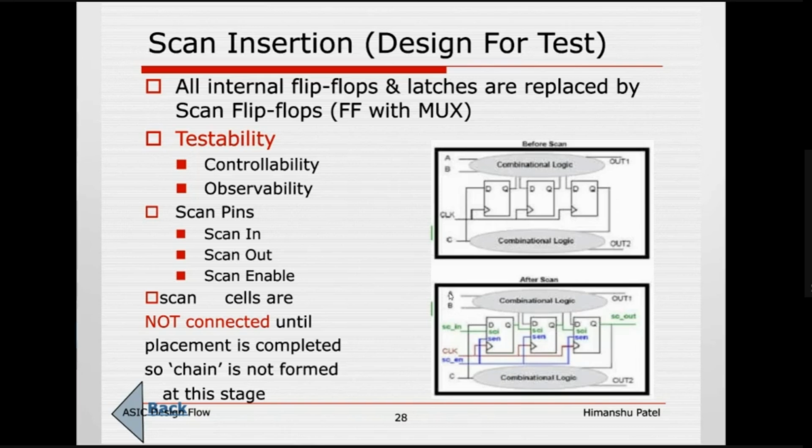But when you have a larger SOC design, with millions and trillions of logic gates, these nanoseconds will become seconds, at least days. When you have more combinational logic gates, the tool will take a lot of time. The runtime of ATPG, the automatic test pattern generation, is very high when you have a larger combinational logic gate count. That thing apart.